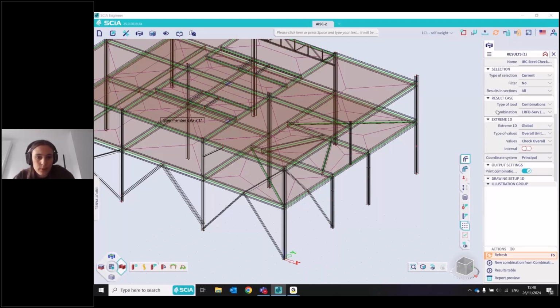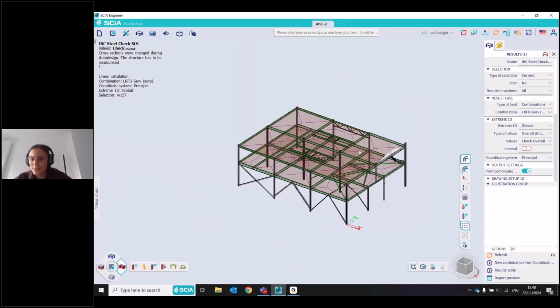Let's select the beam. This will check the deflections in both the Y and X directions. Here they are really good. Maybe let's take a bigger one with a larger span. Maybe one that looks tiny with a lot of load. No, also really fine. So in this case, my project doesn't seem to have many issues with deflections.